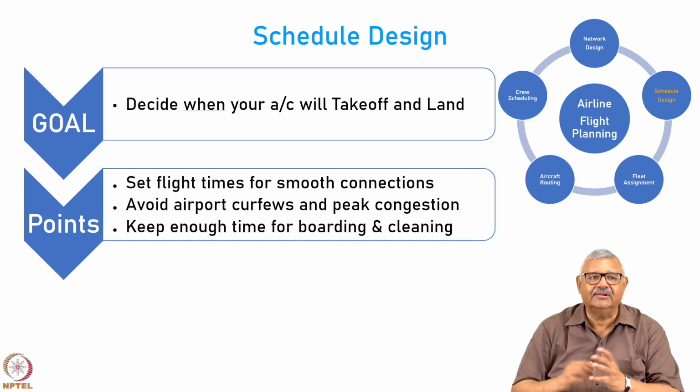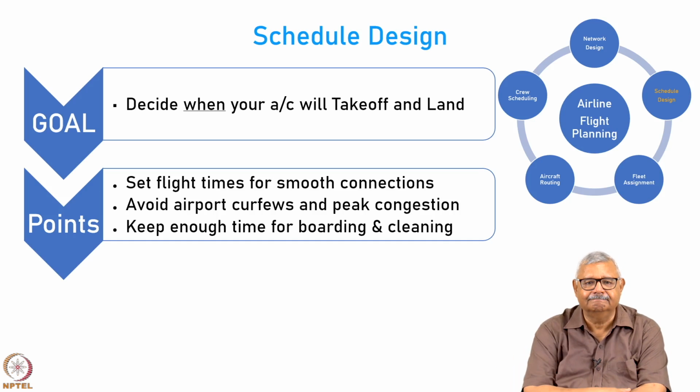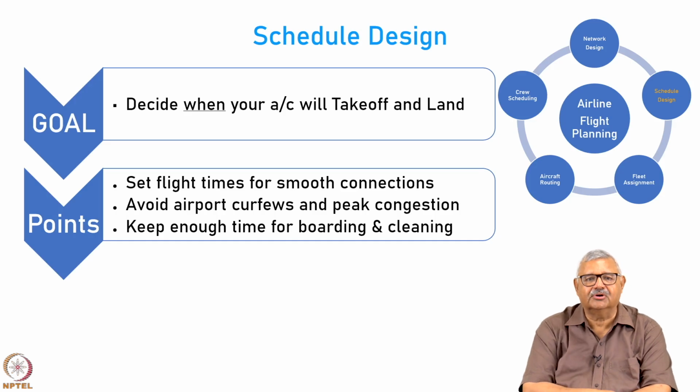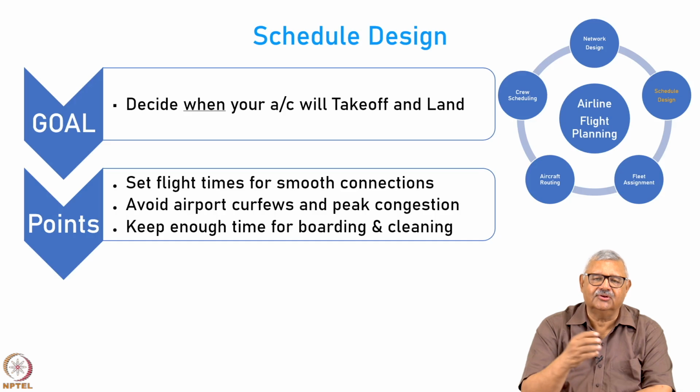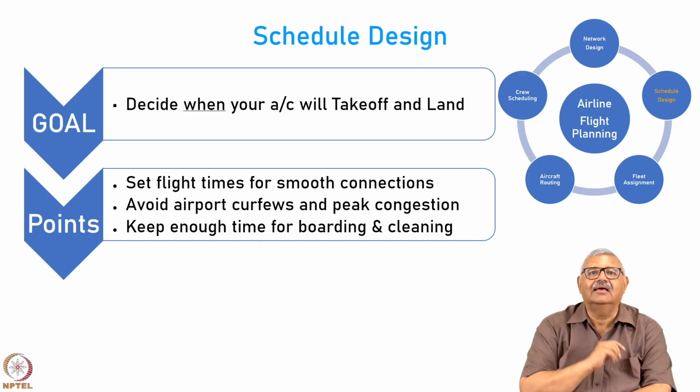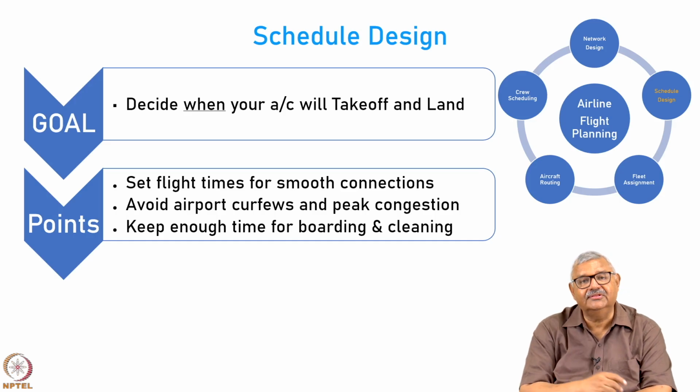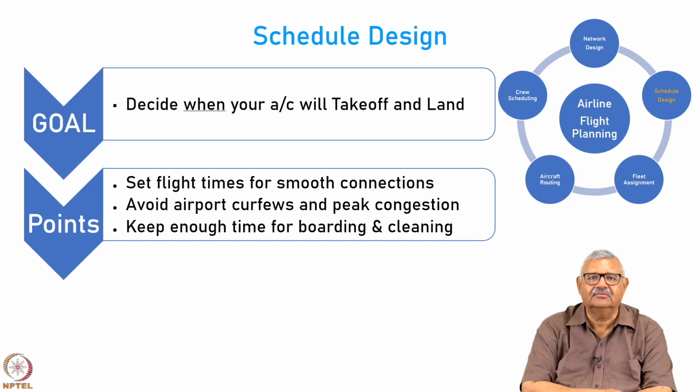Therefore, we have to time them very properly, and that is what is schedule design. You have to avoid airport curfews and peak congestion times. During peak congestion times, early morning and late evening, there is bound to be delay, and therefore either you incorporate that delay in your scheduling itself, or you try to avoid those times, but those could be the busy times or the times when people want to fly, then you have no option.